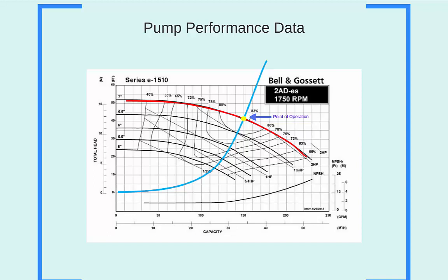The amount of flow that the pump can push through a particular system can be found by plotting the system curve on top of the pump curve and finding where those two curves intersect. The pump will always operate on its pump curve. If the system has valves opening and closing, the system curve will change, and thus the intersection of the pump curve and system curve will change as well. But as long as the pump remains at 1750 RPM, that operating point will stay on the pump curve, which does not change. We will discuss the effects of variable speed pumps in a couple lessons from now.